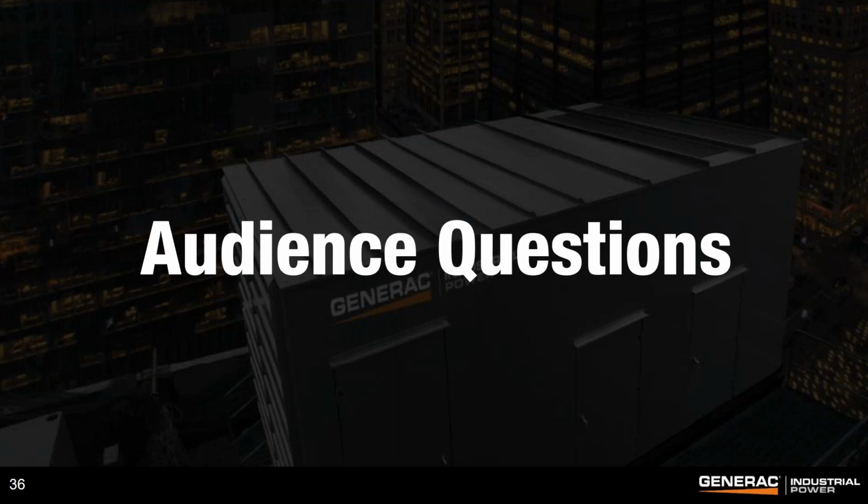Can you give your opinion on overlapping neutral technology? Overlapping neutral, the way I kind of look at it, is a solution for a problem that really doesn't manifest itself in the real world. There's a theoretical argument put forth around the idea of an overlapping neutral, but what happens is the transfer switch becomes much more complex to make the 4th pole operate differently than the main 3 poles.